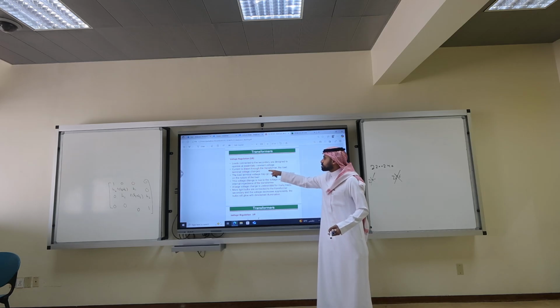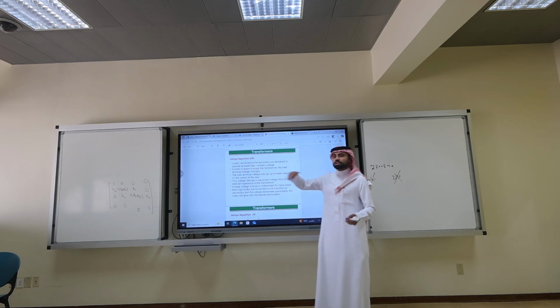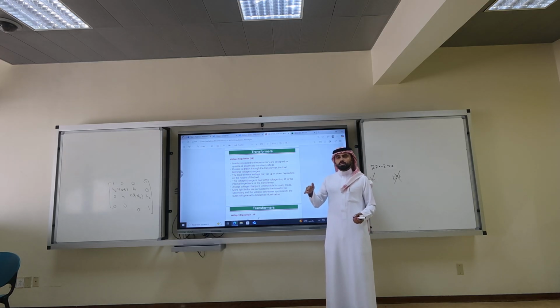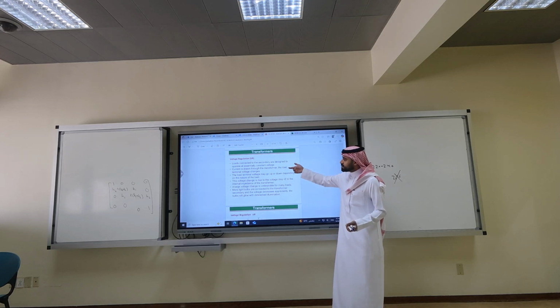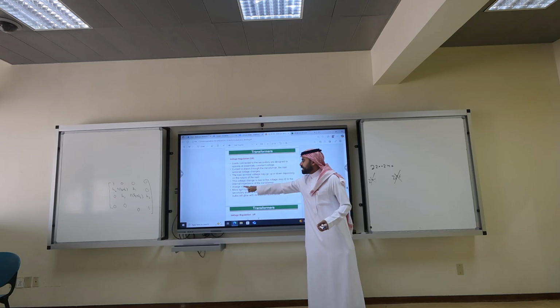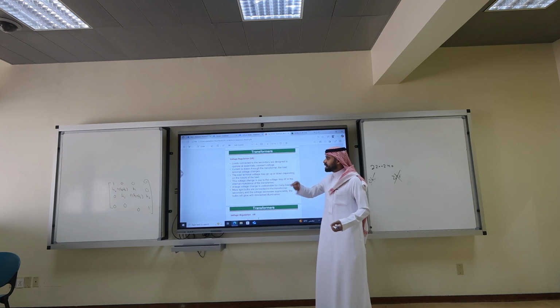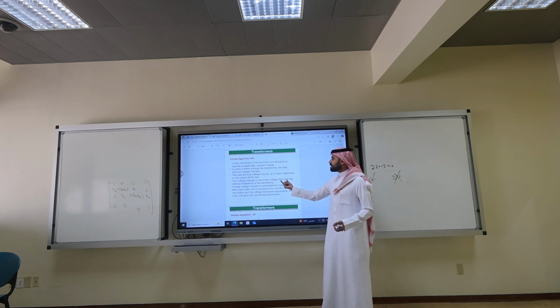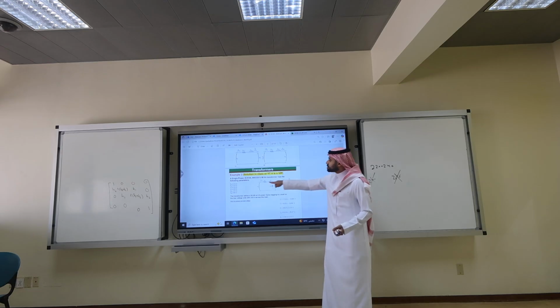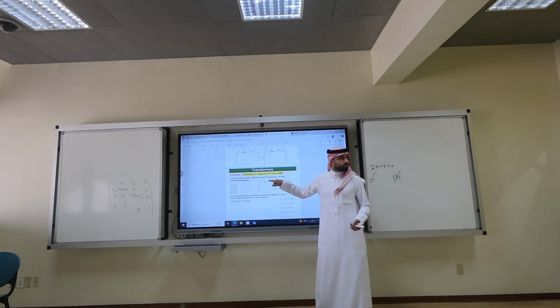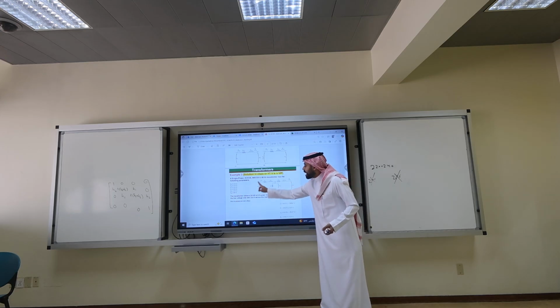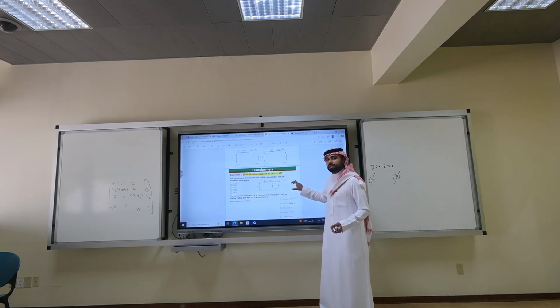When the current is drawn through a transformer, the load terminal voltage changes. In order to compensate for this problem, we need to increase the primary voltage to maintain the secondary voltage. Why? Because every time I have a different current, I have a different voltage drop across these circuits. So if the current is high, I have a higher voltage drop here, and a higher voltage drop here. Then I need a higher voltage here to maintain a constant voltage here.